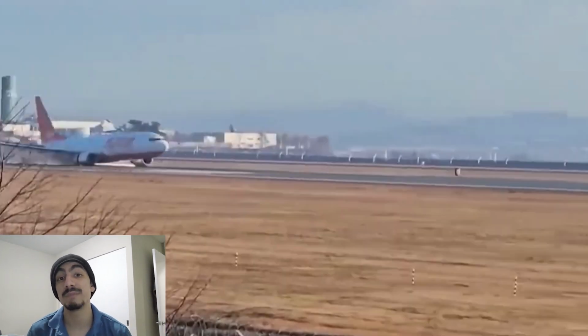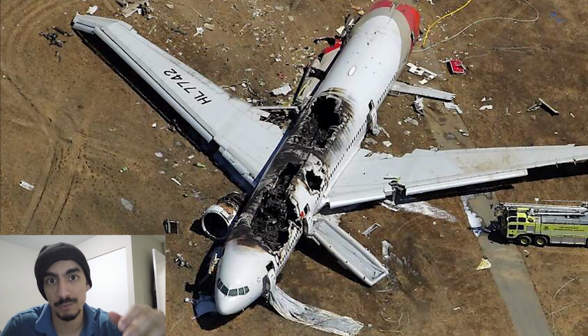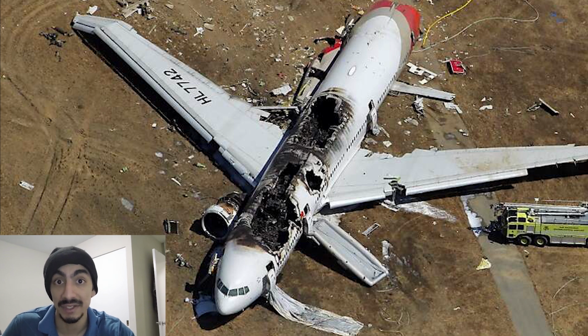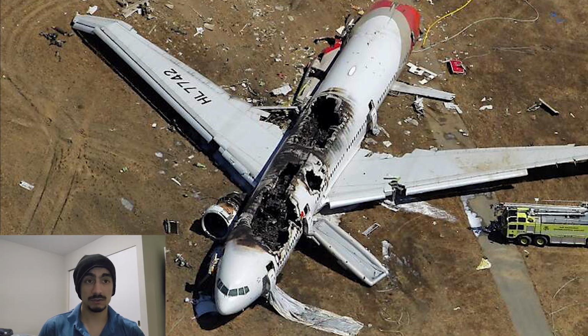So yeah, lastly, in terms of belly landing, there can also be structural shear, which is basically a belly landing tearing open the fuselage. Because planes are designed with very strong underbelly structures, but not necessarily to withstand the impact from a massive load like this at landing speed. And even if the fuselage doesn't rip, you still have engines slung under the wings. Those can break off if they hit the ground first. So all of that wreckage can cut into the wing. It can rupture fuel tanks. It can sever very crucial control lines as well.